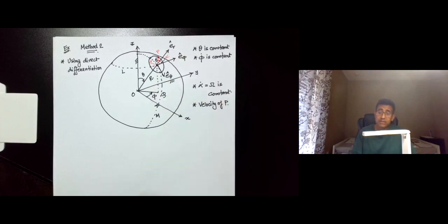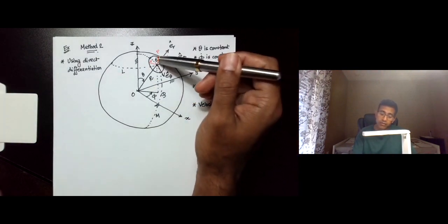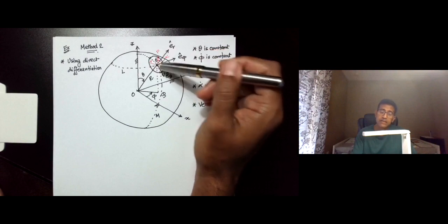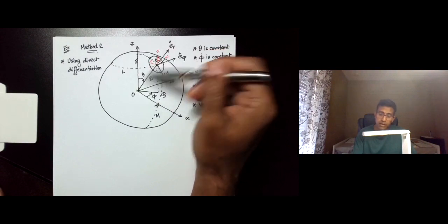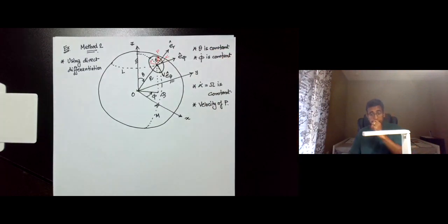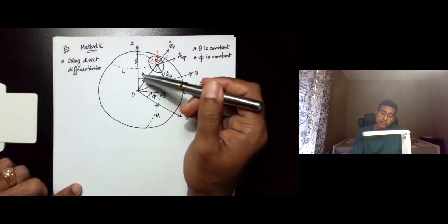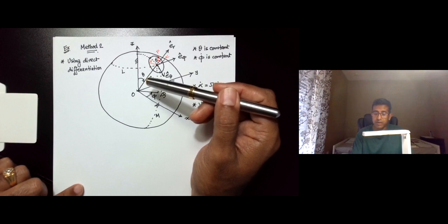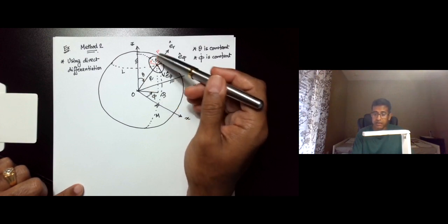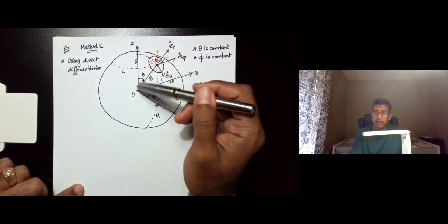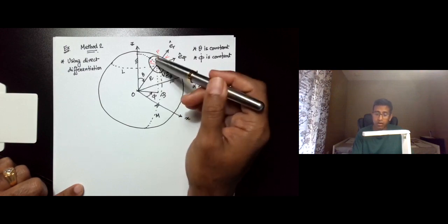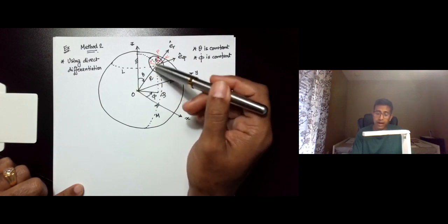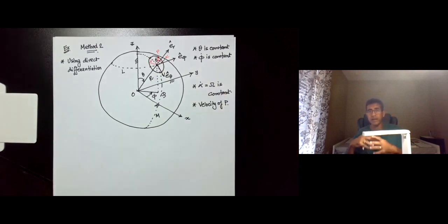And so that is one rotation, and on top of that there is a disk, and the disk is spinning about this rotating bar. So the rotation of the bar is referred to as the precession, and this is the spinning motion, and in all, the rotating bar and the spinning disk is considered as a gyroscope.